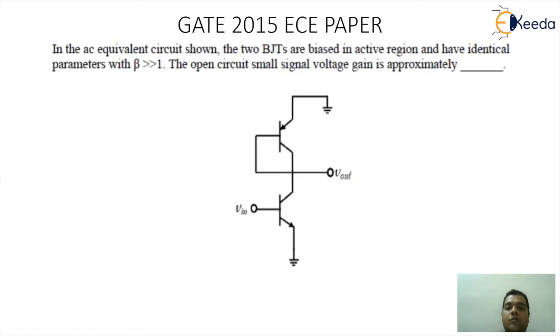So we are having the V_out point at the collector end and the emitter of the PNP transistor is connected to ground. So if your observation is very sharp, the value of V_in with respect to ground will be as good as the value of V_BE for the NPN transistor. And the value of V_out measured with respect to ground will be as good as measurement of the base voltage with respect to ground for the second transistor. So that's the reason when you find V_O, the value of V_O will be V_B2 and the value of V_I will be V_B1. But since the lower transistor is an NPN transistor, the value of V_I or V_in, which is equal to V_B, is going to be equal to plus 0.7.